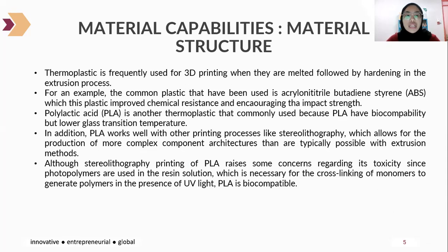Besides that, polylactic acid, or we call as PLA, is another thermoplastic that commonly used because PLA have biocompatibility but lower glass transition of temperature. In addition, PLA works well with other printing processes like stereolithography, which allow for the production of more complex component architecture than typically possible with extrusion method.